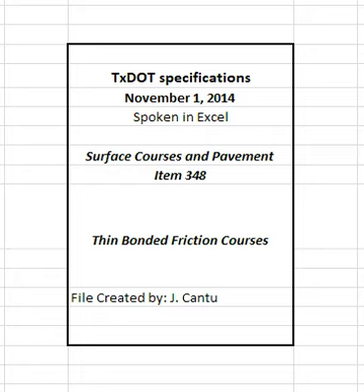4.5.1 Storage and heating of materials. Do not heat the asphalt binder above the temperatures specified in Item 300, Asphalts, Oils, and Emulsions, or outside the manufacturer's recommended values. Provide the engineer with daily records of asphalt binder and hot mix asphalt discharge temperatures, in legible and discernible increments, in accordance with Item 320, Equipment for Asphalt Concrete Pavement, unless otherwise directed. Do not store mixture for a period long enough to affect the quality of the mixture, nor in any case longer than 12 HR unless otherwise approved.